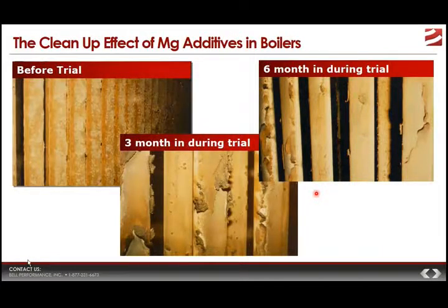And if they say, well, that's too long, the answer is, well, that is the way it is. Magnesium additives are effective. It keeps them from having to go in and blast those deposits off manually. They don't have to shut down. They can keep going in operation, and those are distinct advantages. But it's not something that happens overnight.